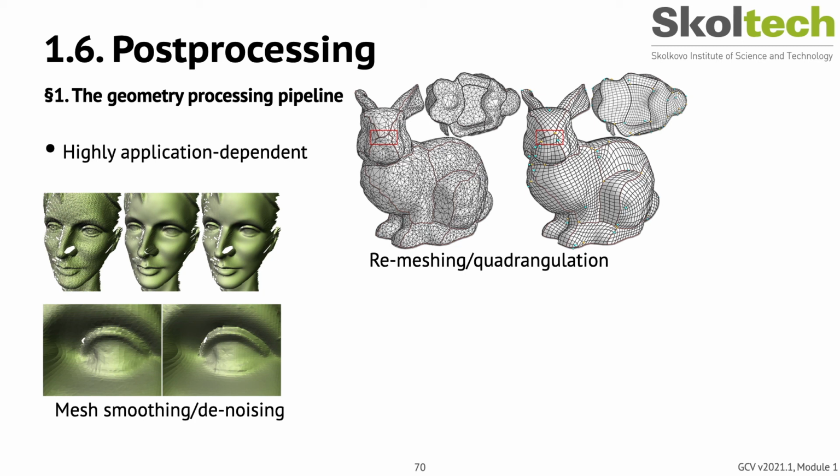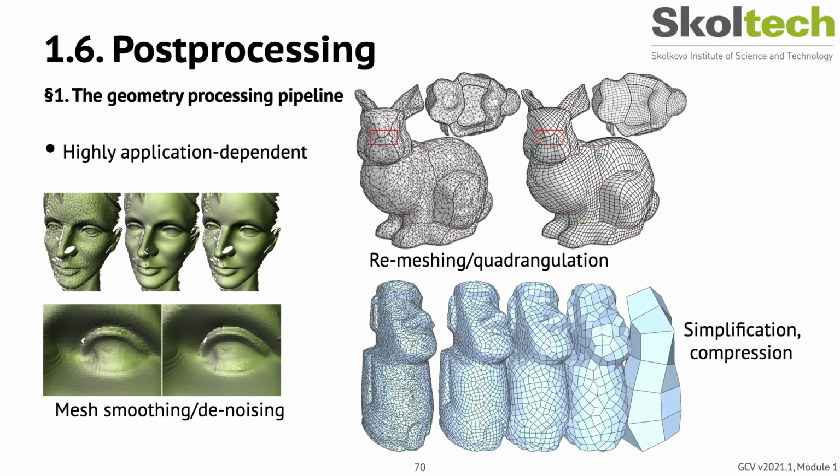Mesh smoothing is a fundamental tool in geometry processing, aiming to construct smooth functions defined on a mesh that can be flexibly chosen to describe vertex positions, texture coordinates, or vertex displacements. The smoothing techniques can be used for mesh parametrization, remeshing, hole filling, and mesh deformation. Mesh simplification and approximation transform a given polygonal mesh into another mesh with fewer faces, edges, and vertices. There are many applications for simplification and approximation, where they can be used to adjust the complexity of a geometric dataset to adjust to computers with varying computing performance.